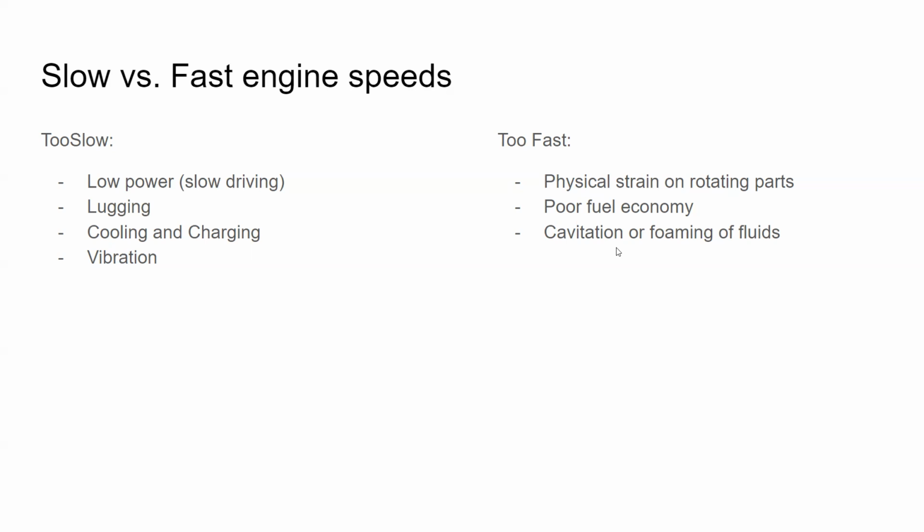If you take a standard automotive engine and you rev it to 8 or 10,000 RPM, it will only last a few seconds before the cavitation of the fluids, the coolant and the oil specifically, becomes so great that the engine basically acts like it's not being lubricated at all and immediately dies. So yeah, higher RPMs, when you're really, really pushing it, can lead to damage because you get fluid breakdowns with your cooling and lubrication system.